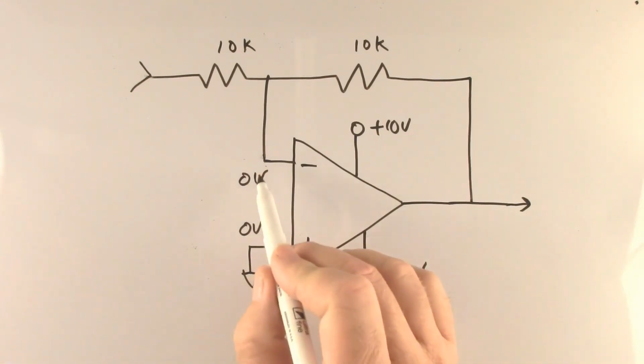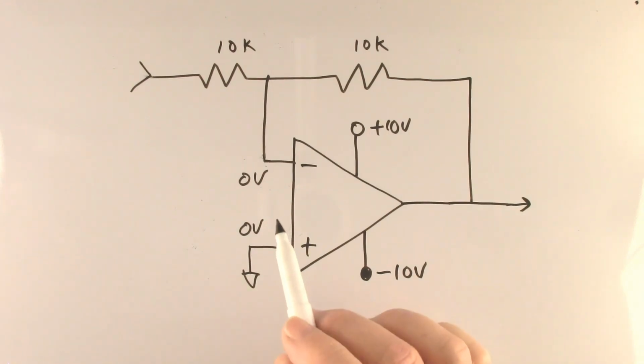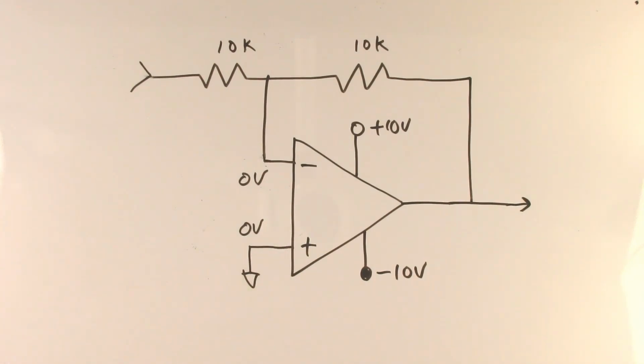This is often referred to as a virtual ground. I'm a little uncomfortable with that definition because, as we know, the definition of a ground is the point where you measure all your voltages from, so that will always be 0 volts, and a ground must also be able to receive or deliver high currents without that voltage changing.